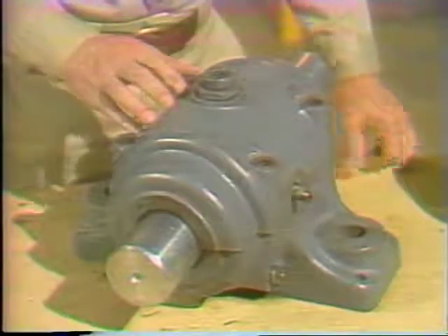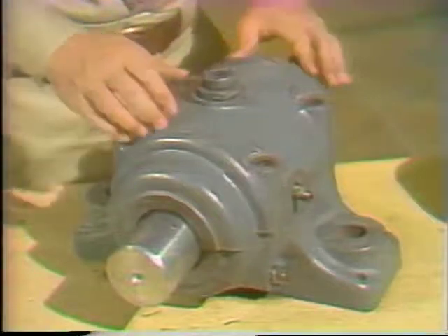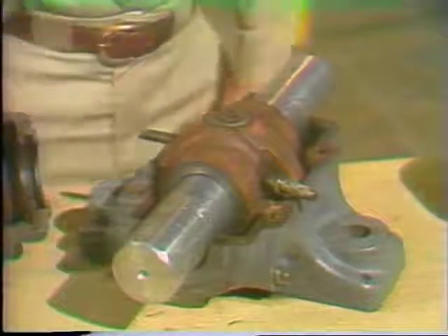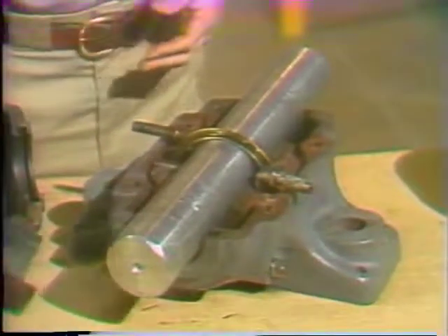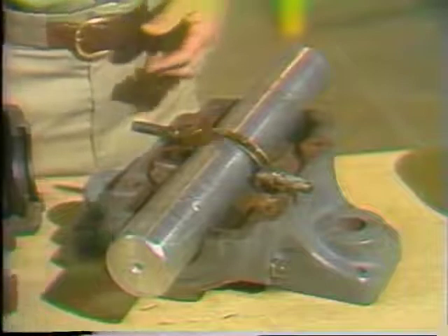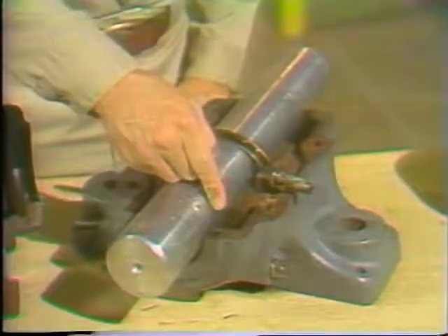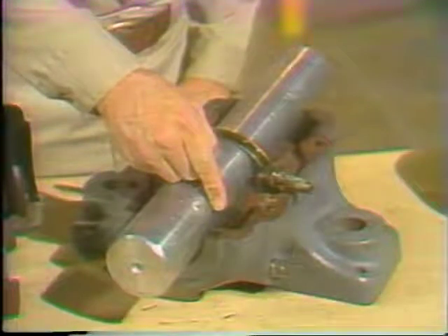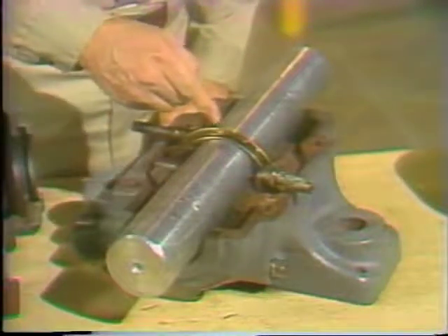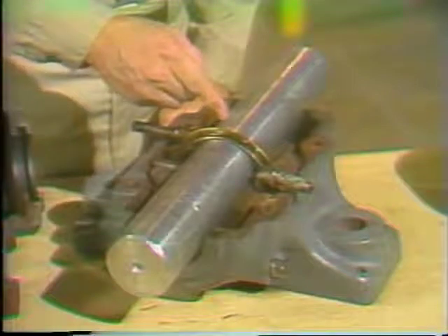Now, as you know, sliding surface bearings consist of a bearing housing which surrounds a shaft. Now, in many cases, the housing and bearing surface are divided into an upper and lower half, like this one, for ease of maintenance. In an oil ring lubrication system, the lower half of the housing contains an oil reservoir, and an oil ring is placed around the shaft.